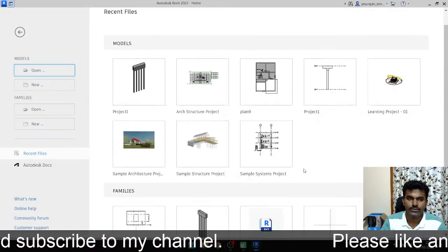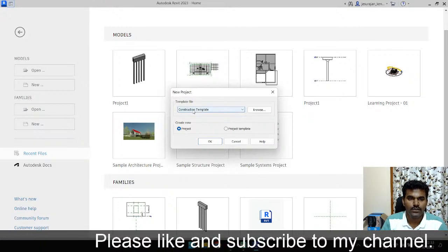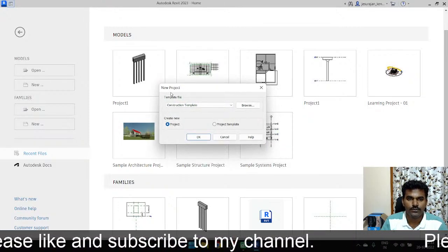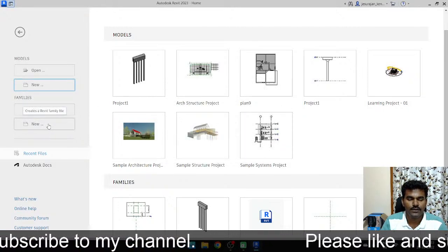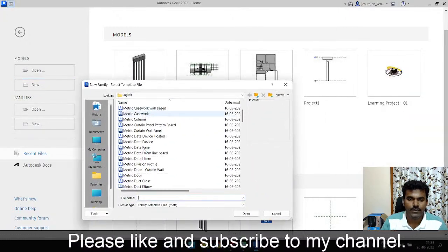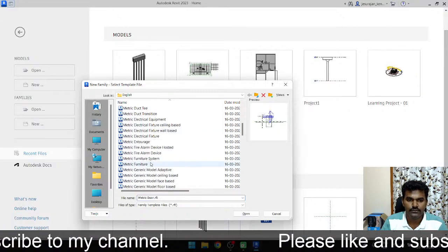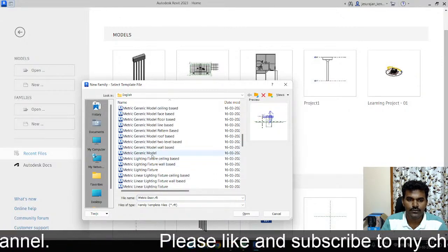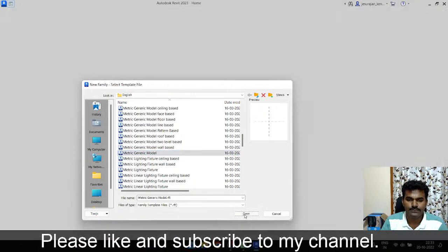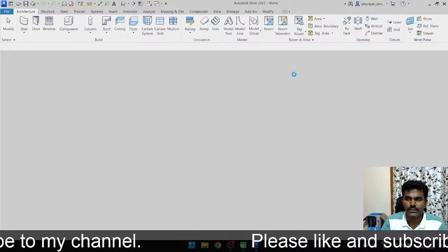Okay, let's go to new. Oh, I just clicked on the project new, so we have to go for families and new. Revit family, let's go for generic model. That's where we start for most of our Revit families. Okay, this is opening.